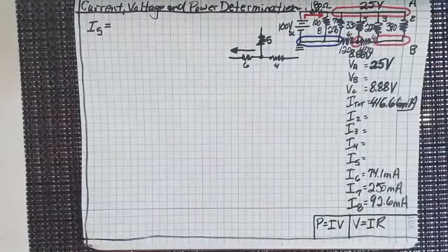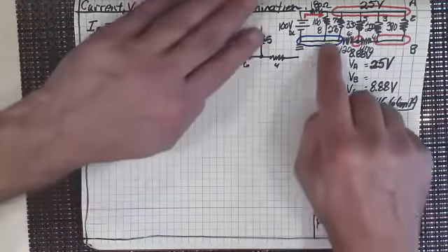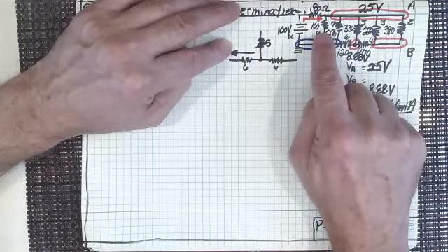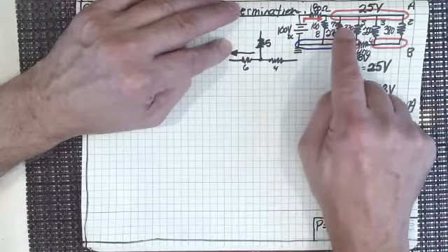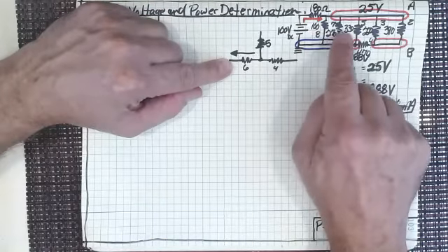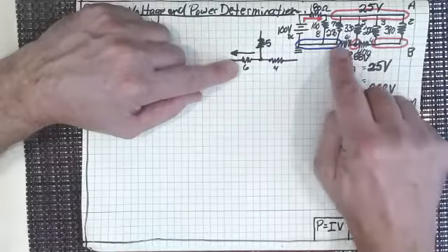Now, that's a node, but it's sort of a boring node because it's 0 volts. But at that node, current was flowing back in through those two resistors, the 100 and the 270 ohm resistor. The only thing that was stopping it from short circuiting out were those two resistor values, right? So they've come back.